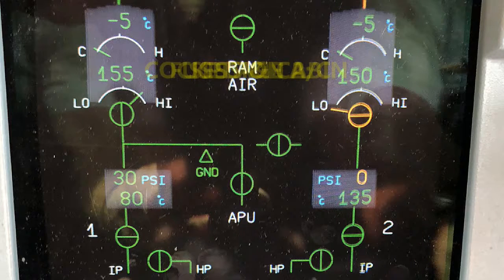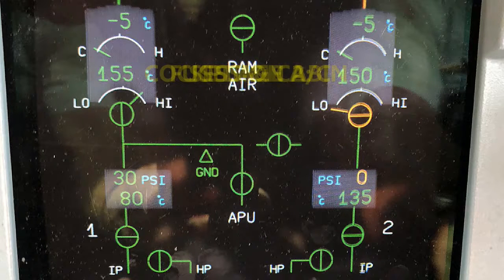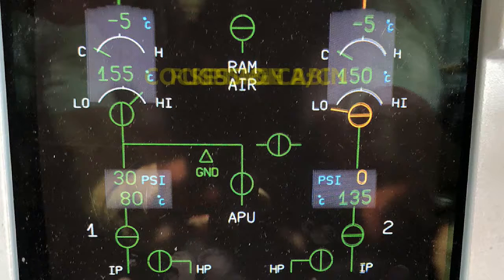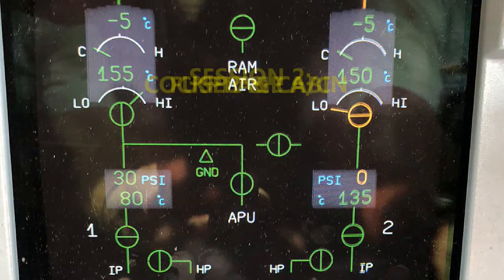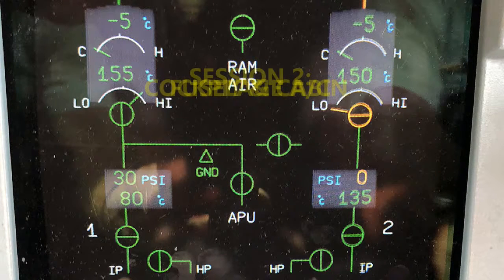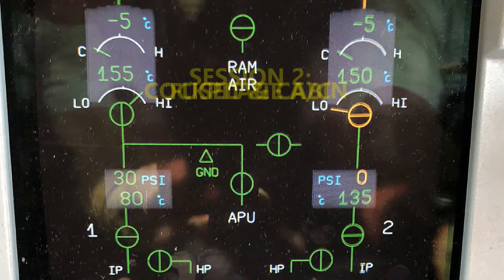It has an internal testing. It's like it has its own little nanoparticles, if you will, because it fixes itself, and it does its own test. It's also going to give the FADEC the bleed air valve status. So that's the kind of information that it's getting and giving to the pilot in the cockpit. It's going to give BITE information on the wing anti-ice system, also for the PCs, the pack controllers, and any BITE information on itself, the zone controller. It's also going to perform an overheat detection and corrective action, because remember I said it's going to correct itself. It's going to do its thing to fix itself.